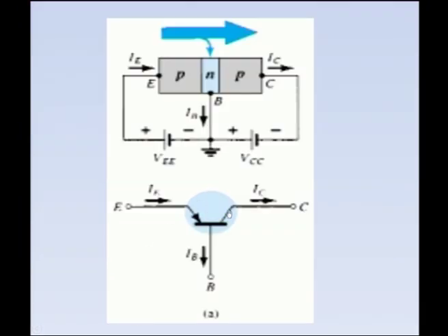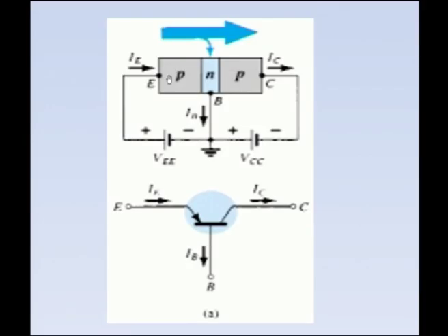If you are ready to draw a circuit diagram of a common base PNP transistor, first you have to note down which part is sandwiched between the other two terminals. Since it is a common base, the base terminal must be sandwiched between the other two terminals, which are emitter and collector. The emitter is the input terminal for the common base, and the collector is the output terminal. And also you have to know the biasing condition of the transistor.